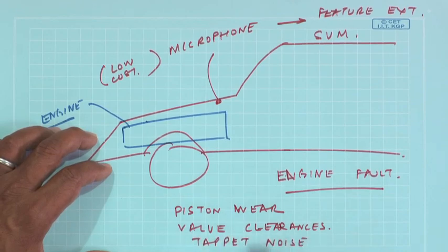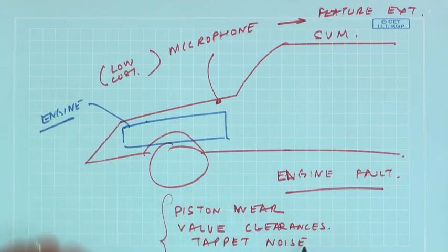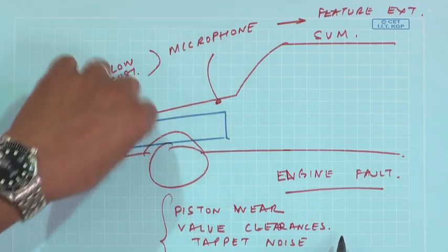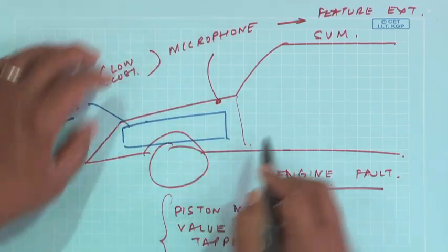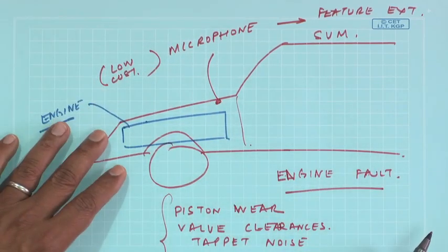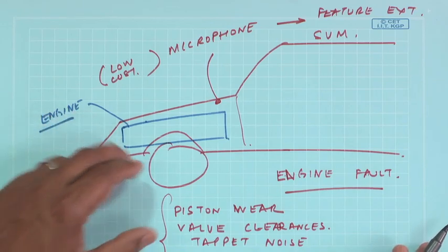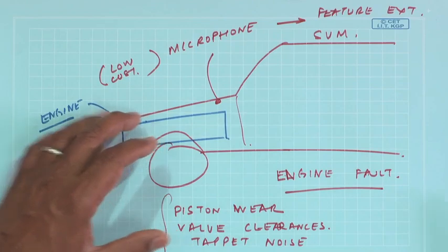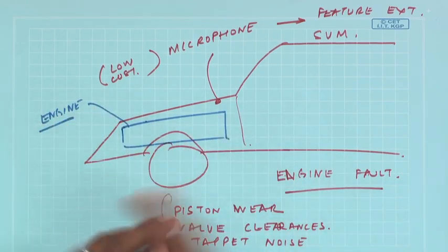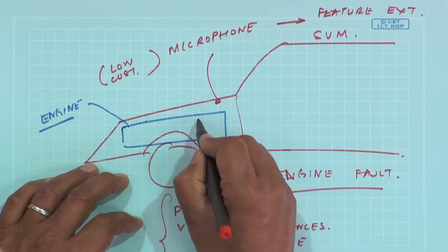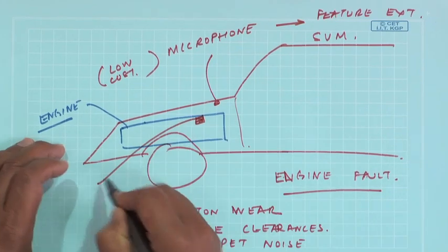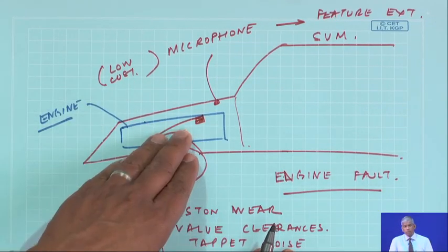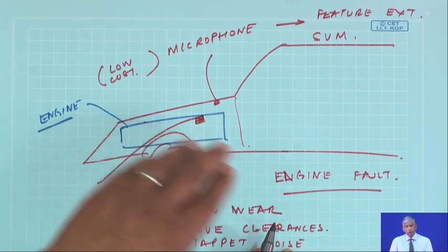So, all these could be very easily quantified, because if the engine is covered and nicely enclosed, the contamination from outside noise is not there. And this being airborne, a lot of the structure-borne issues with traditional vibration measurements are avoided, because if I put a vibration transducer here, it is going to measure all sorts of vibrations because of the suspension, because of the engine, because of the transmission.